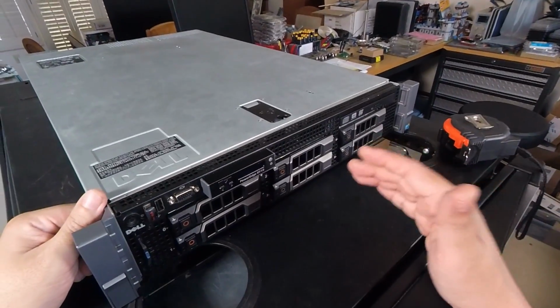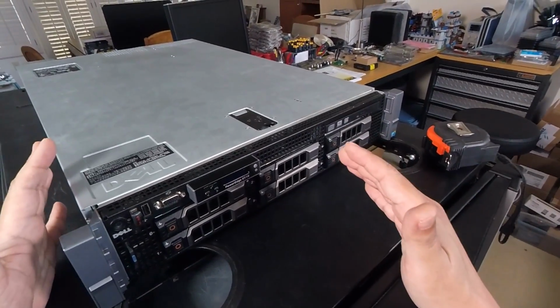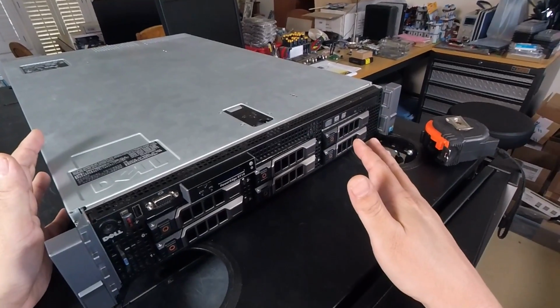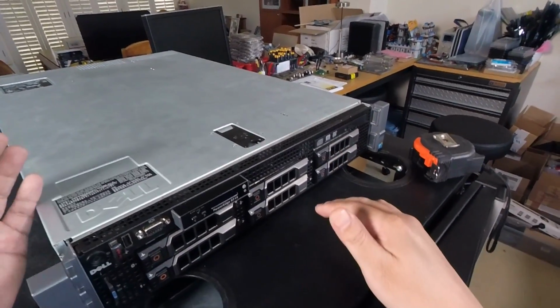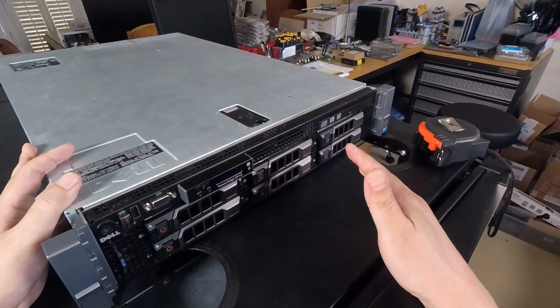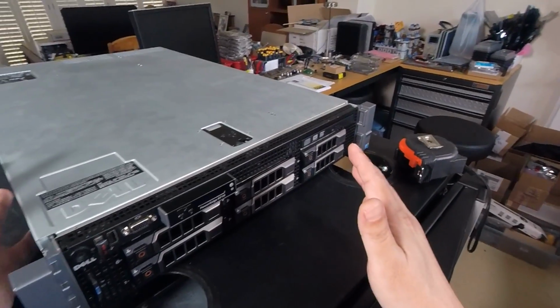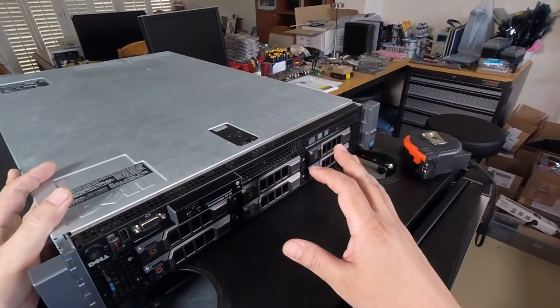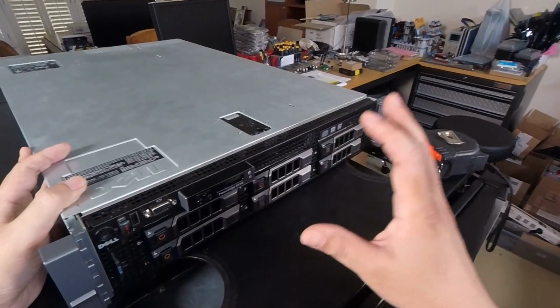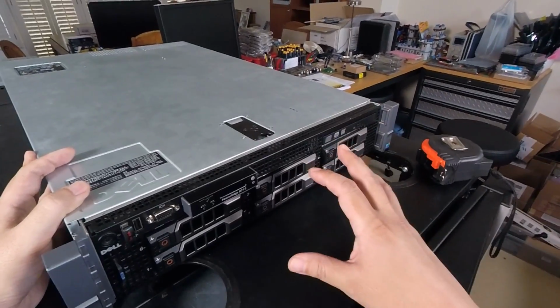Now, along the lines of compartmentalization, I'm going to take measurements without any hard drives first, and then I'm going to repeat the results with hard drives. And the reason for that is because hard drives can make a significant portion of the overall power consumption and heat generation of the server.